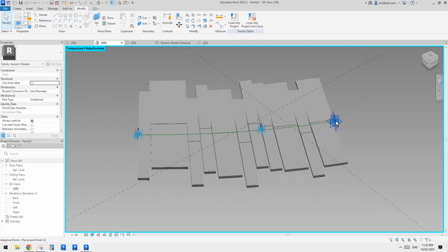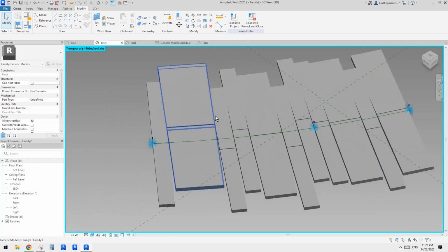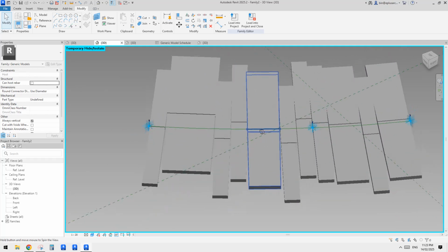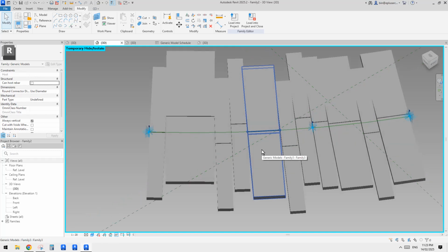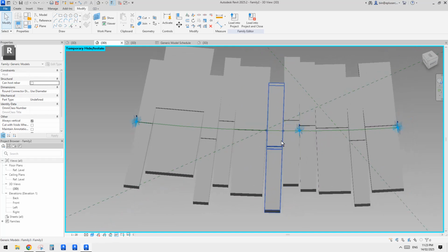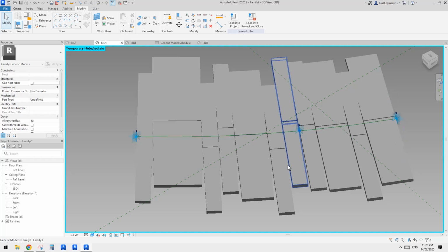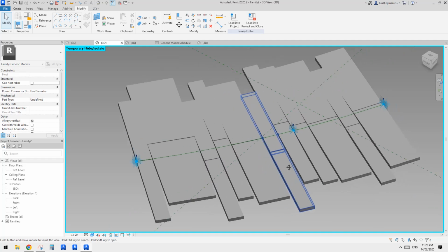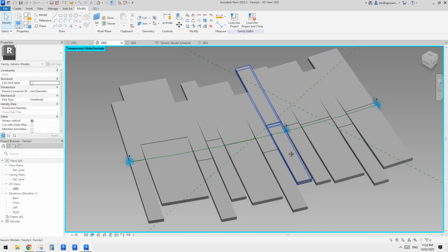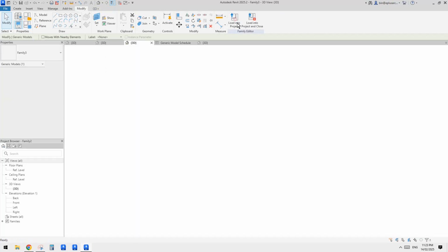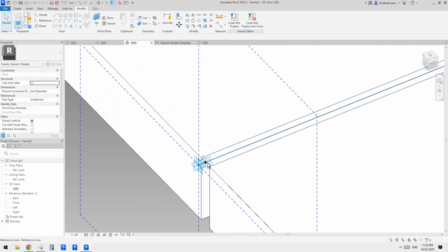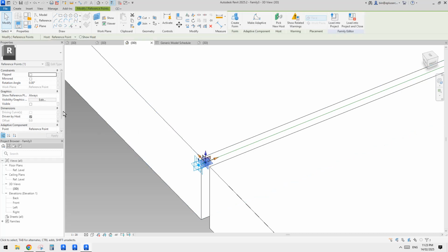in the next family, so it will create this. So what we need to do for this one, I think, is probably just maybe increase the gap a little bit, right? It's probably the easiest, because we don't want to make this one even not rectangular, trying to have the exact 10 mil gap. I don't think that's necessary. So let's just go into here, so we can just increase the gap a little bit maybe. Or you can just ignore that at all.